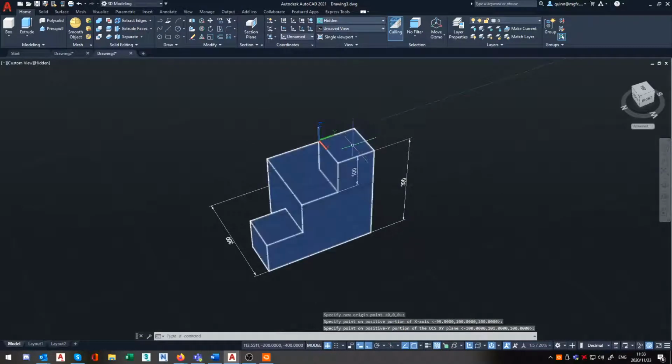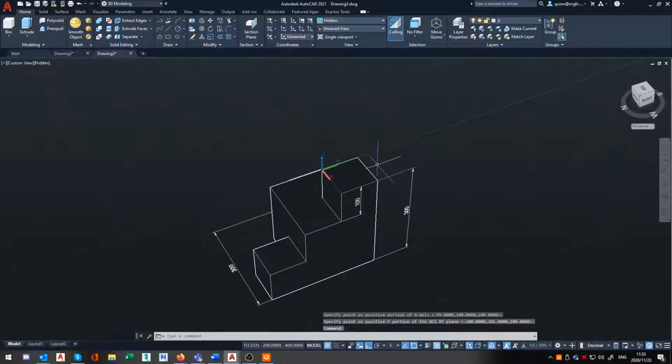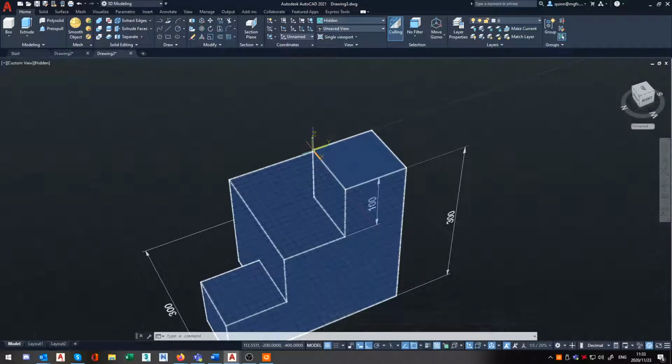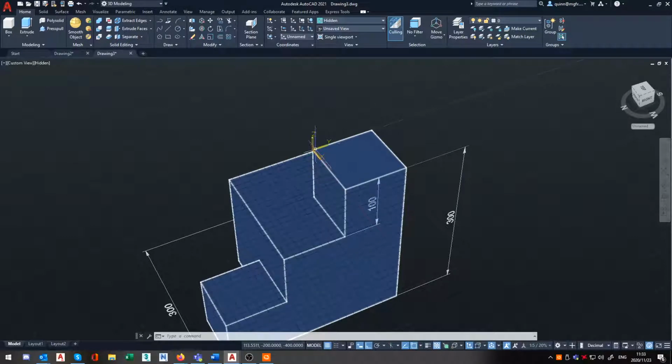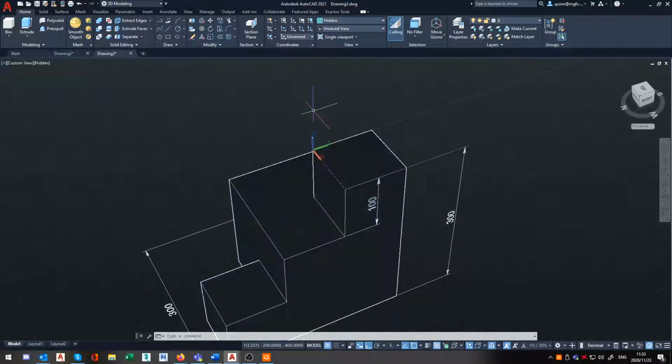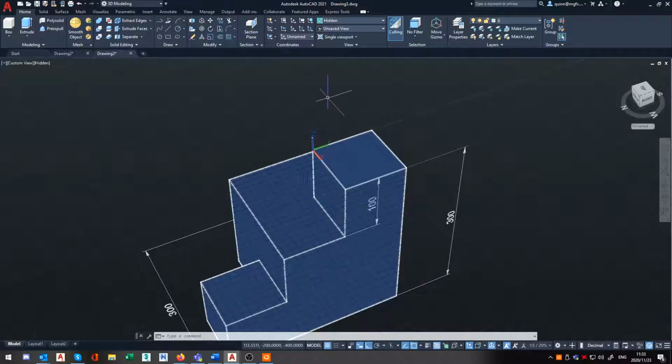Now you'll notice that even though it's 3 points, people might get confused here because I've only specified 2 of them. I have actually specified 3 because I specified where it is, the base point, that's your first point. I specified my x point, which would be my x-axis, which was running down this section. And then I specified my y point, which is running in that direction. Because I've specified the positive of both the x and the y with its origin, it then knew where to flip the z, pointing up. Remember when I pointed it to the left, the z flipped down.